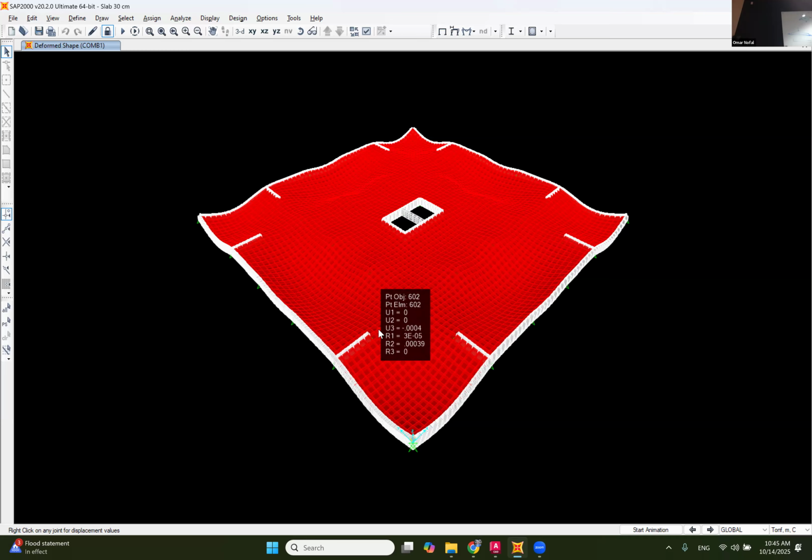When you have a building with a flat slab system, sometimes we put a marginal beam around the slab system. It's called marginal beam. But look at what happens here. Has deflection. Doesn't have any. Why? Because we put two supports and this is acting like a wall. We made it to act that way. How? We put two supports at the start and the end, and we make that beam very, very stiff. So you barely have deformation at that beam.